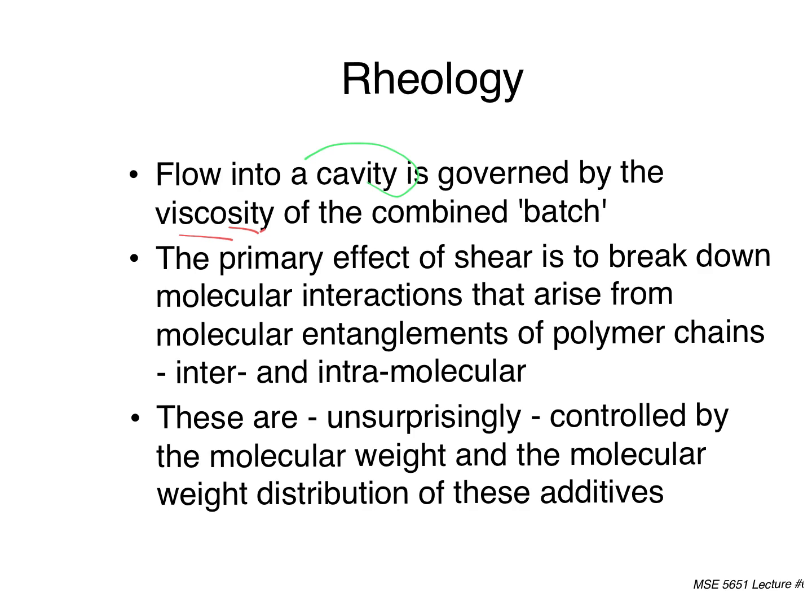And what we often do is use shear in these processes. This is something we're going to do a lot. I think the biomedical guys have homogenizers, which are based on shear. Those are used to break tissue up into soup, basically. You drop your finger in there and it turns it into soup in 2 minutes or something like that. So that's done by shear, which means that two surfaces are moving past each other very quickly, and that breaks things down. In this context, it breaks down molecular interactions that arise from entanglements of different polymer chains, both inter and intramolecular, meaning between different polymers and within itself, and that's necessary to help mix things together. You can't have a big hunk of polyethylene and a bunch of alumina separated from each other. You have to mix them together, and that mixing has to be very intimate, as you'll see.